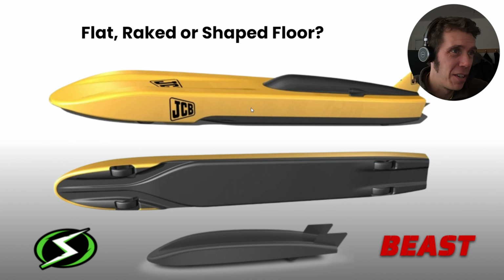And finally, I was also seeing this JCB Diesel Max design, which in a similar way has actually got a shaped underfloor. It's got these little vanes here that take air in at the front and then send it out of the sides, which then probably creates a vortex that goes down the side and aims to take air away from the front of the rear wheels, which would generate a bit of lift, which is obviously undesirable on a land speed attempting car. So those were my inspirations behind my early design exploration.